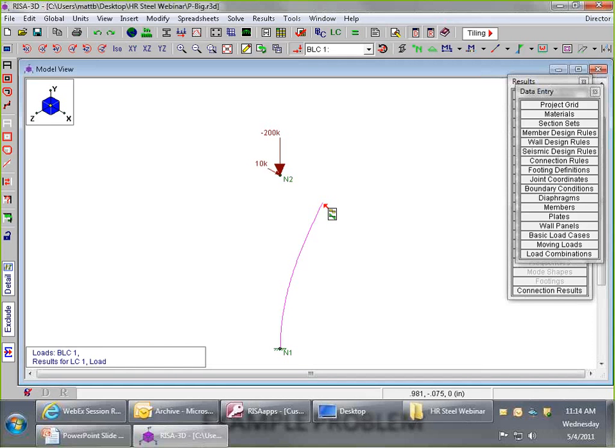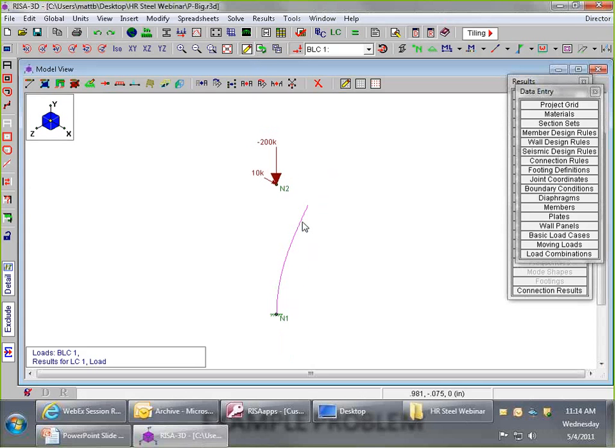It ends up becoming a multi-step process. You see, inherently, when we solve without P-Delta on, what we're looking at is what's known as a linear analysis. That is, the farther that I push, or the more load that I put on this column, the farther over it's going to bend in this direction. But we're not accounting for additional factors, those being the secondary moments that are going to add up in the column and that are going to lead it to want to collapse. So what we can do is manually take a look at what the P-Delta effects are going to be on this column.